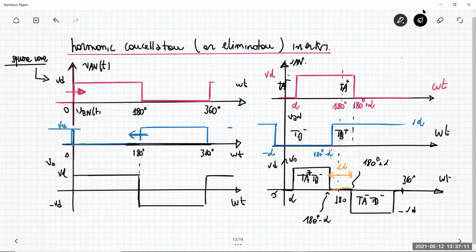So these two 0 levels are obtained by both the high side transistors or both the low side transistors being on. More or less typically the switch combination that we have in the unipolar PWM with oscillator. Remember the 4 different states of the switches that give us 3 levels of variation.